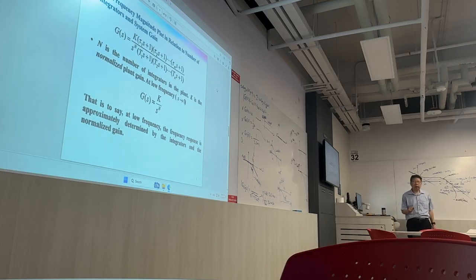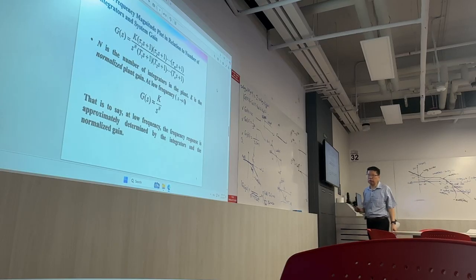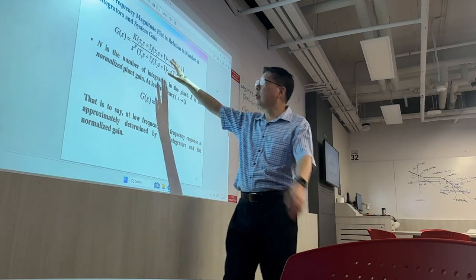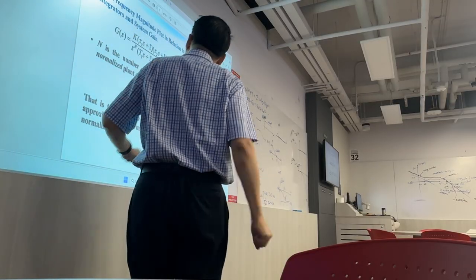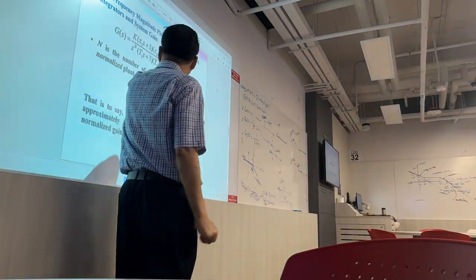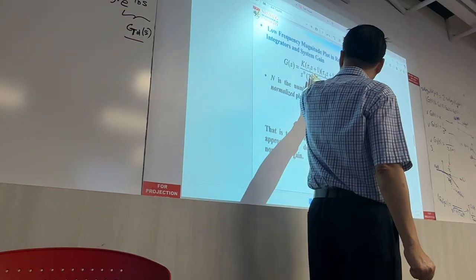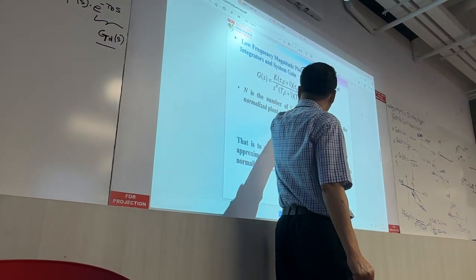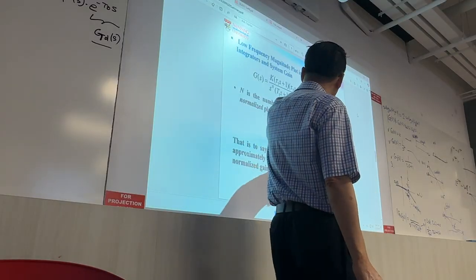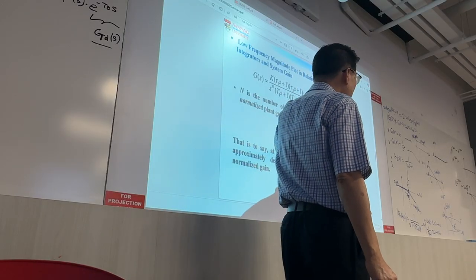Then we look at some characteristics of these Bode plots. You look at this overall transfer function, you can rewrite it in this way. For lower frequencies, all these will be relatively small compared to 1. You drop them, so you get the approximation as K over s to the n.